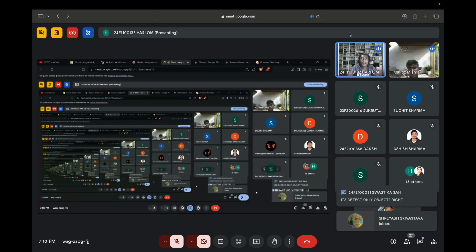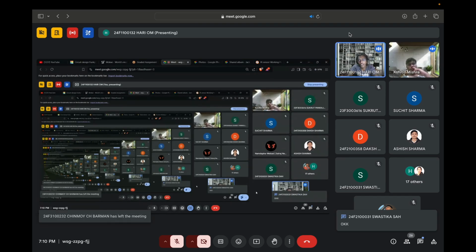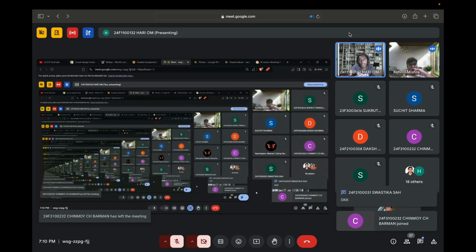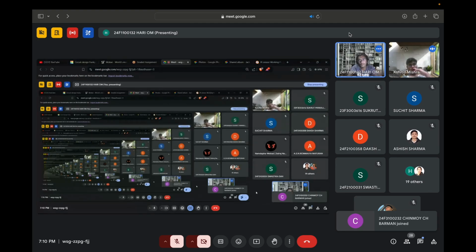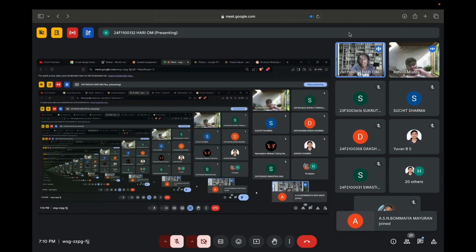If we take it out in the sunlight, if you buy a cheaper one like this one, it will detect IR waves automatically from the sunlight. And if you buy a more expensive one, it will send the signal in a pattern. If the receiver LED sees the same pattern, then it will go high. So it will work in sunlight also.